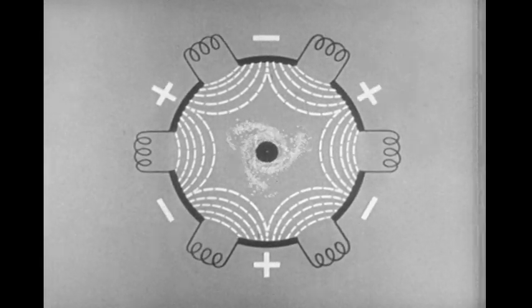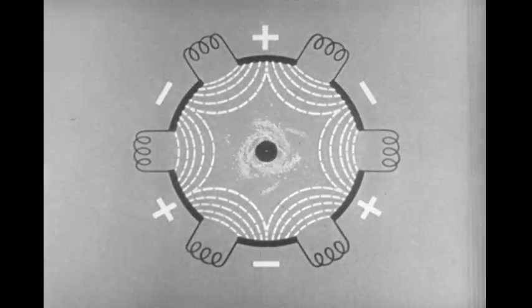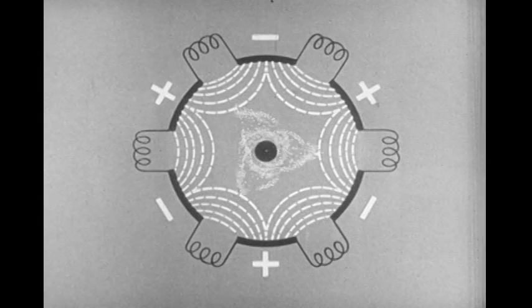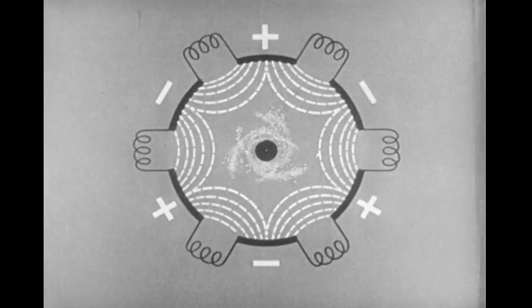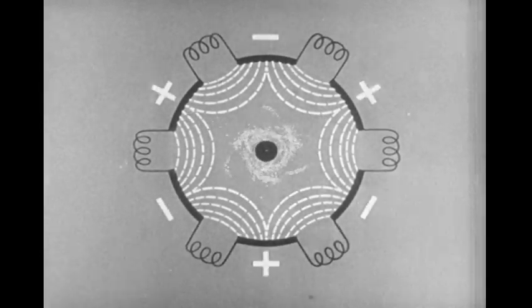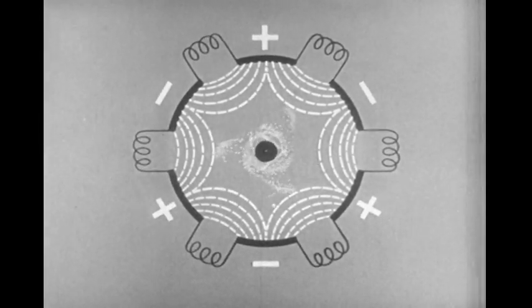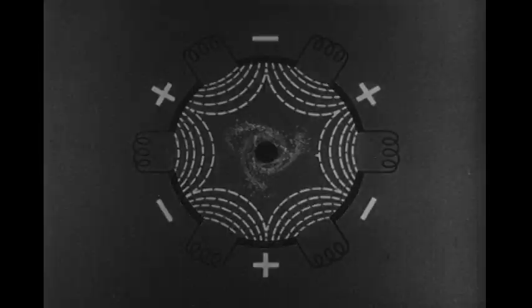And the clouds will revolve in the same direction as the individual electrons, always approaching an RF negative segment of the anode. In this way, the kinetic energy, which the electrons obtain from the DC potential, is given up to the RF field, and oscillations are sustained.